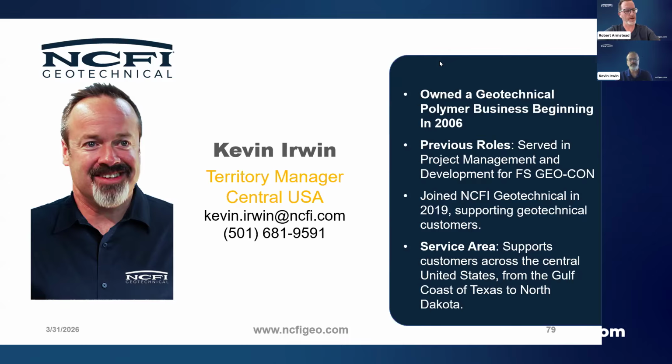Along with that question, there was: how do you assess the amount of foam that will be accepted by the soil? Obviously, pore space is important there, the pore space in between the soil particles. So clay soil is going to accept less than sandy soil, or you go to that Crowne Plaza project we looked at briefly. You've got huge pieces of riprap, big chunks of rock that we're trying to fill in between.